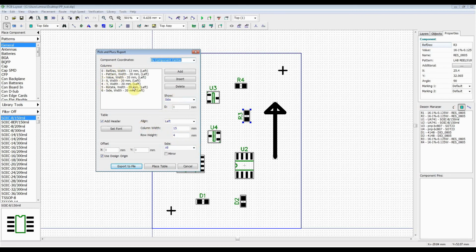To set these up, basically you set the line. You say either add, delete, and what have you, so you can edit what the line is, and you can change what the line actually denotes. You only need to do 7 different values. You do not need to know the width and heights or the names, the generic naming component. What you need to know is the other stuff. So just slowly add them in: Ref des, pattern, value, X, Y, rotate and side.